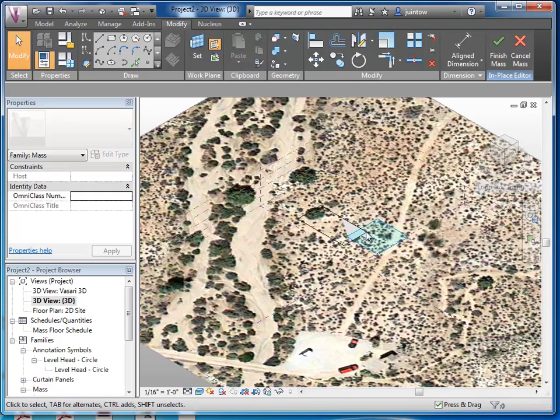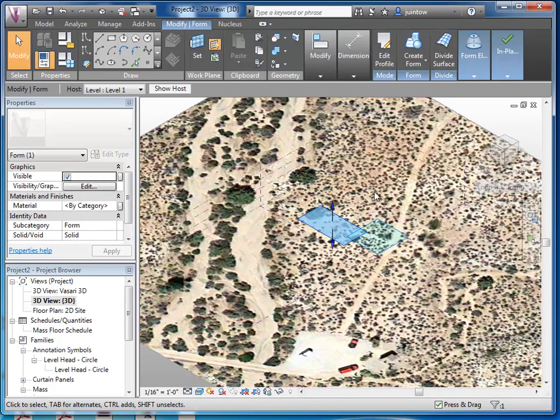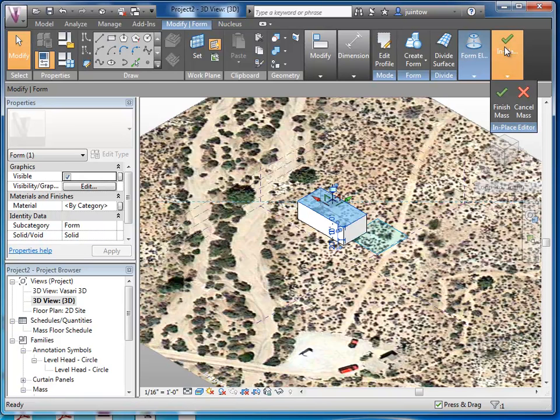And then once I have this surface drawn on the ground, I need to extrude it, okay? So your buildings are probably like 1 or 2 stories, so just extrude it up to, it snaps to level 2, okay? And if you want, you can lock it into that. This is about Revit and being able to make things parametric, but for now it's not that important. Just make it up to level 2. And then let's just hit Finish Mass.